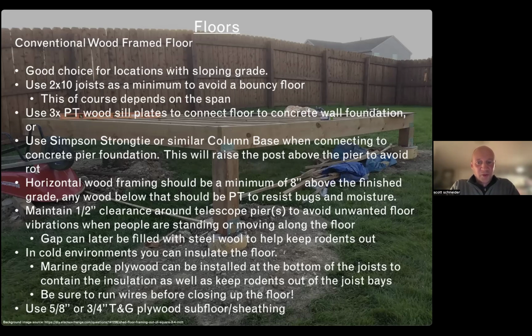The building code and lumber suppliers have charts showing maximum spans for lumber, so it's always good to check that out. But as a starting point, 2 by 10s is a good place.